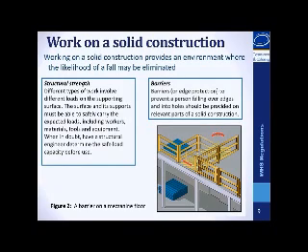Structural strength. Different types of work involve different loads on the supporting surface. The surface and its supports must be able to safely carry the expected loads, including workers, materials, tools and equipment. When in doubt, have a structural engineer determine the safe load capacity before use.